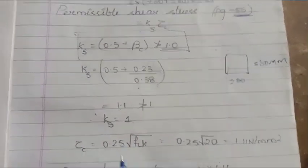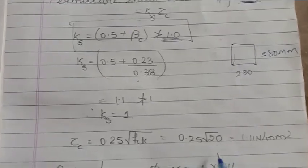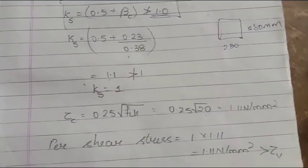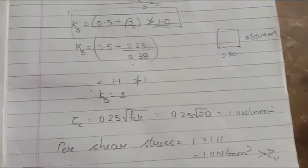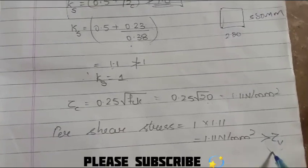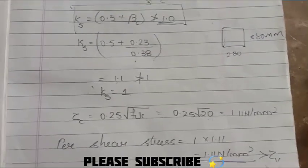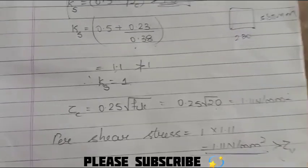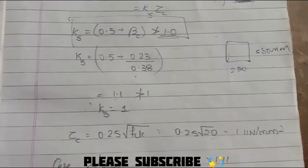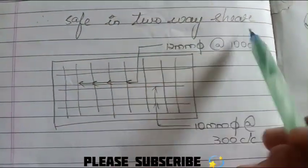Next, tau c is nothing but 0.25 root fck. The fck of the concrete is considered. For M20 we are designing, take it as M20. You will be calculating the tau c. Remember, tau c should always be greater than tau v, because tau v is nothing but the load that is acting, and tau c is the value for which we are designing. Whenever we are designing, we have to design for a greater value than that which is subjected. As tau c is greater than tau v, it is safe in two-way shear.